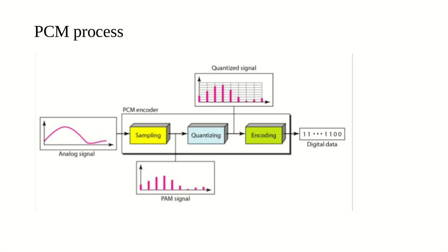Then the sampled signal is quantized. The result of sampling is a series of pulses with amplitude values between the maximum and minimum amplitude of the signal. After quantization, we approximate the value of the sample amplitude to the quantized value. The quantized values are then encoded as streams of bits. After this process, to recover the original signal, it requires a PCM decoder. The decoder first uses circuitry to convert code words into a pulse that holds the amplitude until the next pulse.